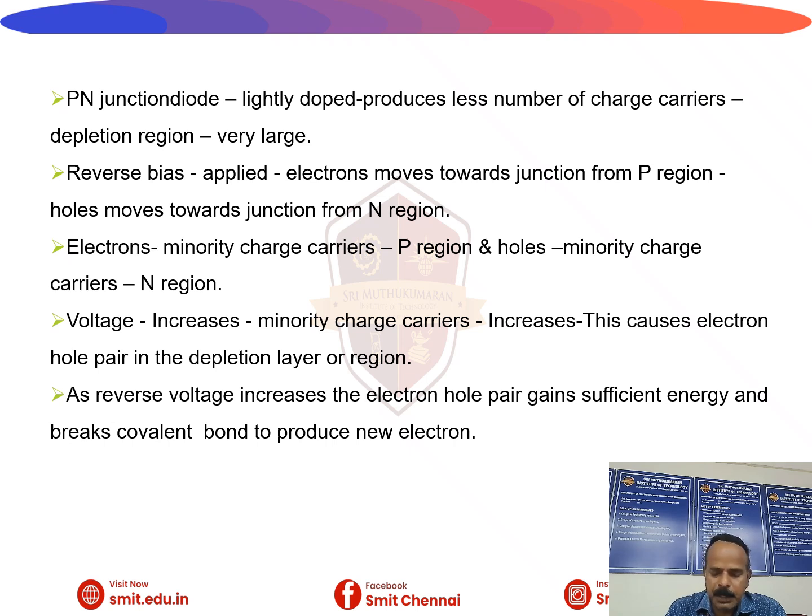This happens because in the breakdown region, a large change in current results in only a very small change in voltage. Therefore, the Zener diode acts as a voltage stabilizer. By connecting a suitable series resistor to limit the current, the Zener diode can safely maintain a constant voltage across the load.